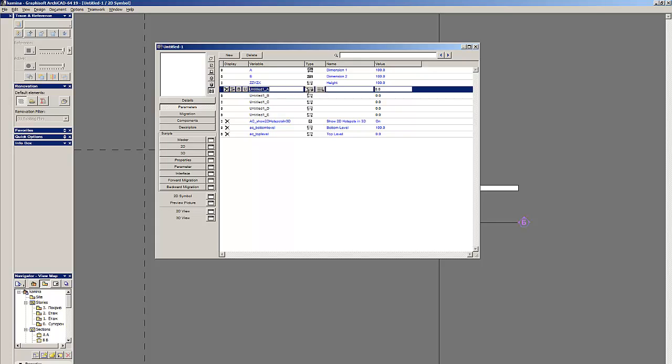Let's name our parameters. First let's name parameter 1, which will be leg length and leg width. These are the two parameters. We will use ZZ, YZ, ZX for the height of the table, A for the total length, and B for the total width. I advise you to use these variables, which will make the object stretchy. If you use other variables, of course you can make it stretchy too in 3D, but it's harder.